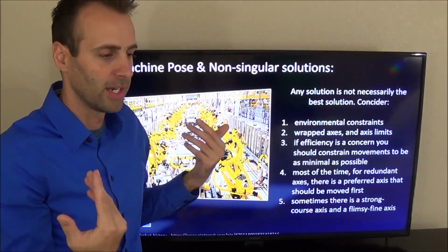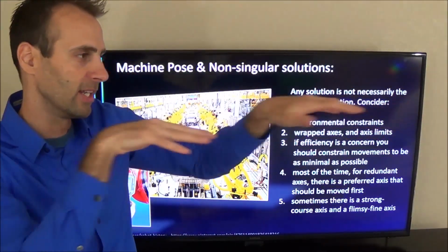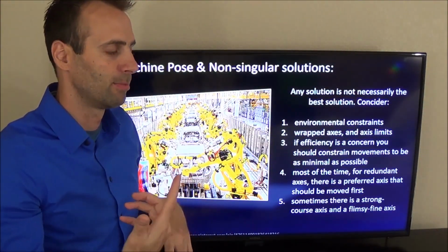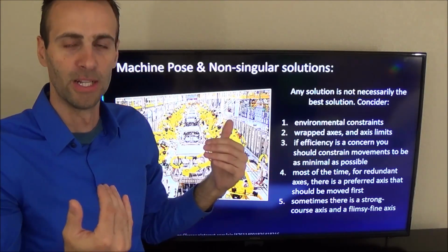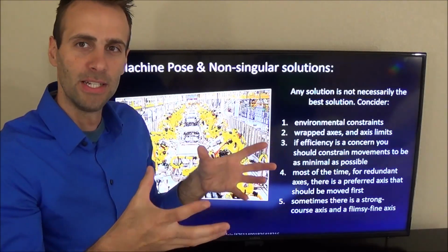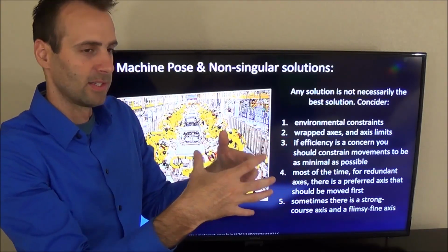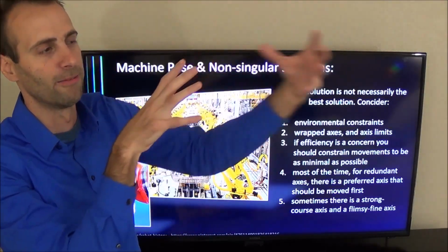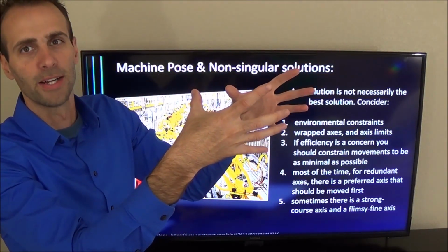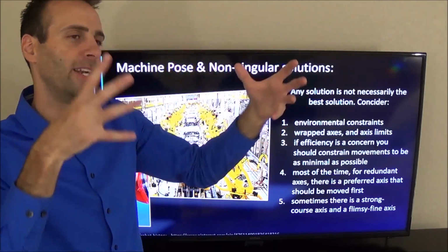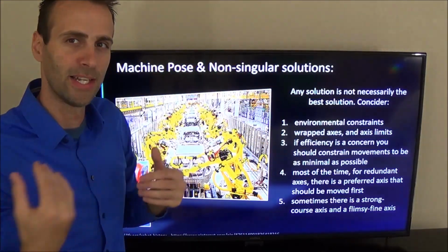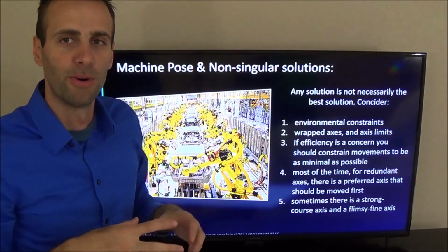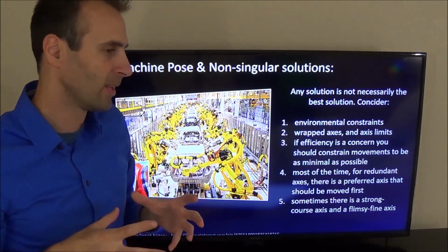Just like on a Bridgeport, you can unbolt the thing and slide the head in and out. That's not a controllable axis, but it's still an element that you can change. So on these big CNC machines, say it looks like a Bridgeport with the table on the bottom and a Z-axis hanging off the frame, this thing unlocks the brakes, moves the whole head up and down, and then relocks. But that's not something that you're going to do while you're machining. It's just there to give you a little bit more flexibility in the parts you are machining.